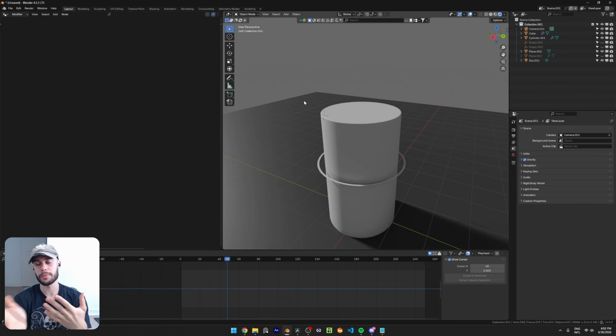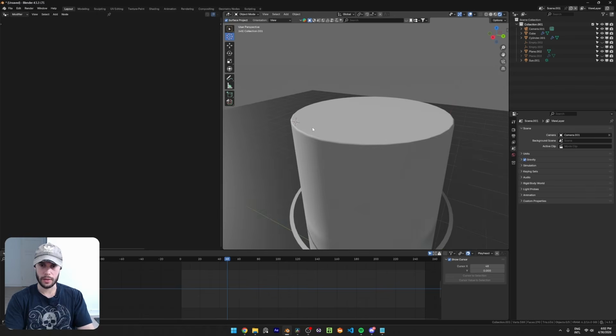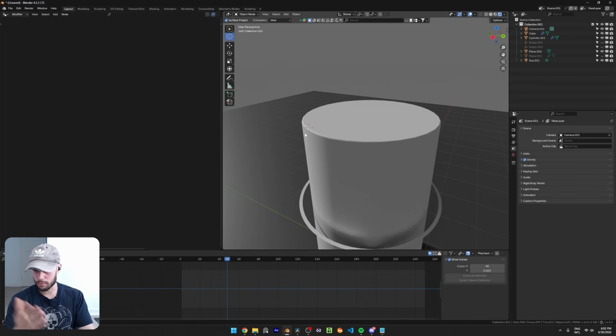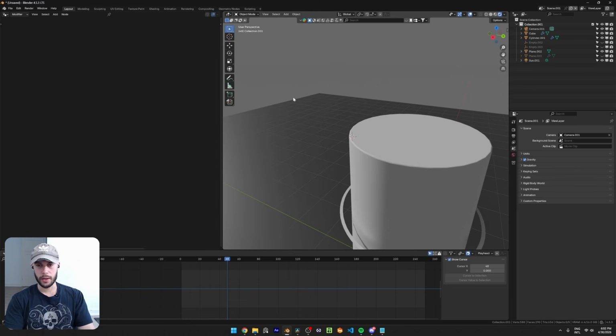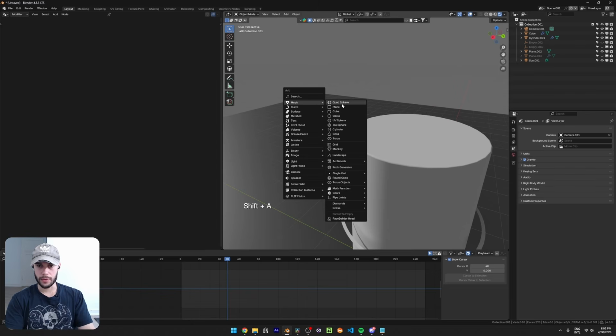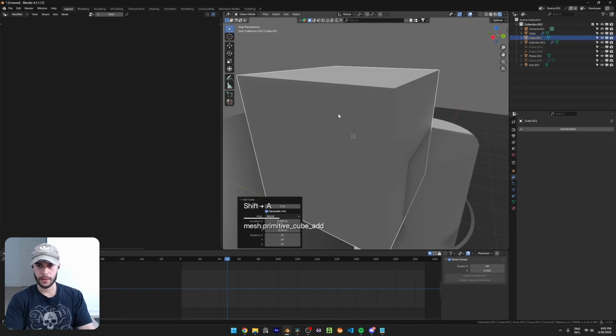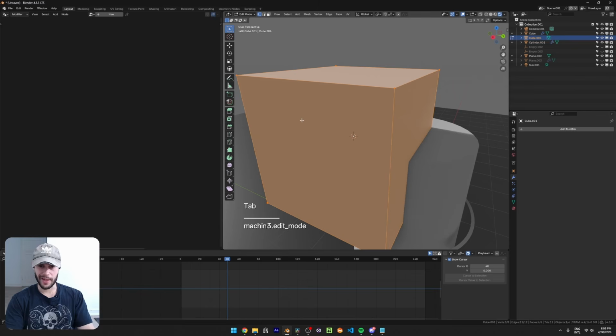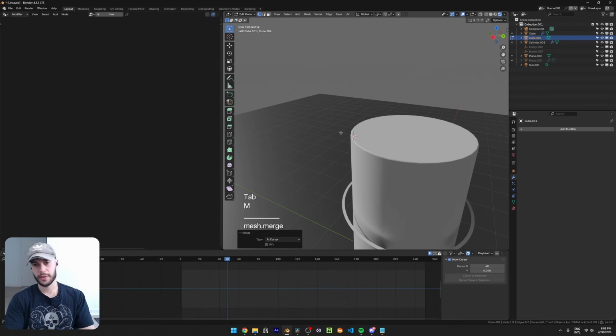So let's go another step higher, and this will be using geometry nodes, but also some other methods so that it's a bit more flexible for us to work in the viewport. For that, let's just put our 3D cursor somewhere we want to annotate, let's say there. So now we are out of geometry nodes, and you can go here, a single vertex, can also go to cube, go to edit mode, press M, and By Cursor, so merge by cursor. So now we just have one vertex where the cursor is.